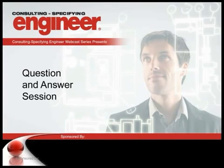Just to give you a quick example, I had a facility where we had separate service entrances from the utility with single transformers, so our fault was not that high on the utility side, but we had a single energy plant backing it up. So we had a combined parallel generator system. So our fault on the generator side was more than our utility side.